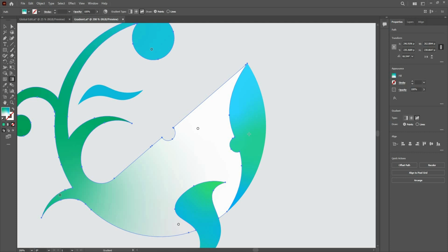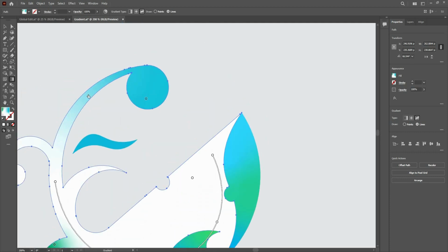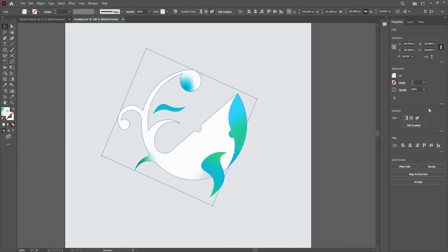The one thing we did was with the points, and the other way will be using lines. So here we have a draw points or lines option. Let's just go to lines this time, and just like the curvature tool, it will draw a curve wherever you like to follow the shade here. So I'm going to draw a whole curve throughout this shape. Alright, there. Now I'm just going to press escape, and yeah, you can assign colors now.